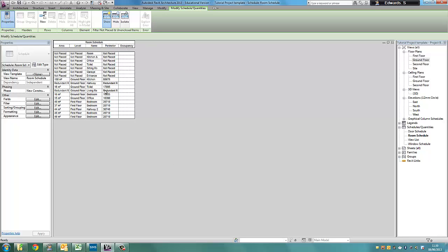It doesn't have an occupancy, and like I said earlier, do you know where the living room and the hallway were connected? It showed that the area and perimeter of the room is a redundant room, so it's a joint room. So it doesn't actually show a perimeter or area. I don't know why they haven't shown up the type of level and the perimeter on these rooms.